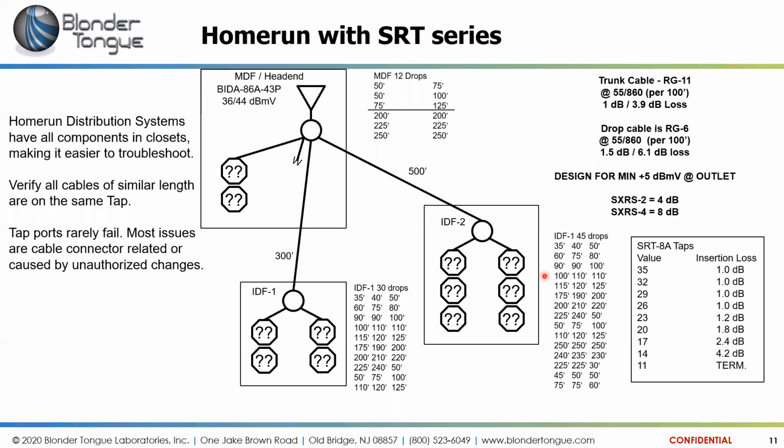So how does cable fail? Well, cable only fails if it's interfered with, if it's cut into, if it's not been installed correctly and it got pulled around a sharp corner and the jacket got torn or something like that. Over time, a rat may get to it and start gnawing on it. Somebody runs a picture hanger into a wall and inadvertently hits the coax. I've seen it happen. External changes to the system is what primarily causes cable itself to fail.